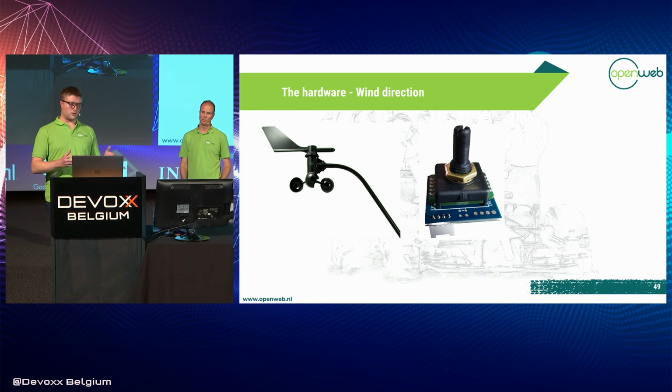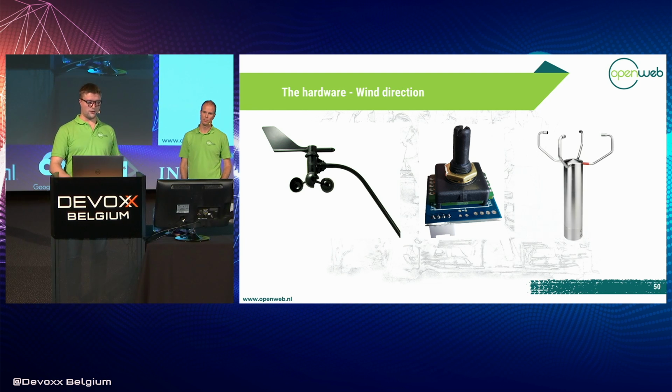But the problem with this one was there was too much friction on the sensor itself, so we had to put almost twice as big a vane on top of it as the left one. So we were looking at a newer version. This one is not the one that's going exactly on the boat, but it will be a much smaller version, and it gives you a precise look at how it works.